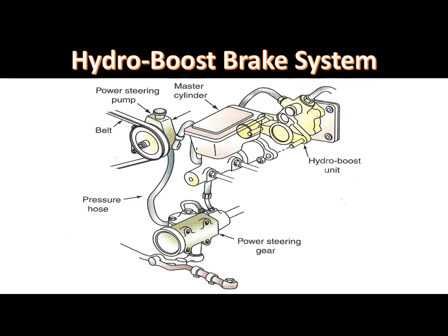When the brakes are released, power steering pump pressure forces fluid through the hydro boost unit, but this pressure is not applied to the master cylinder pistons. If the brakes are applied, brake pedal movement operates a lever in the hydro boost unit and opens a valve that supplies power steering pump fluid pressure to the master cylinder pistons and provides brake assist.